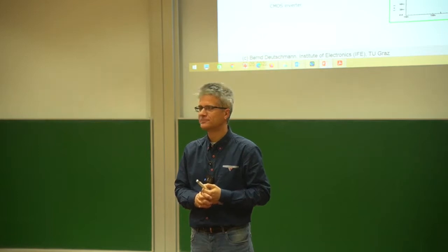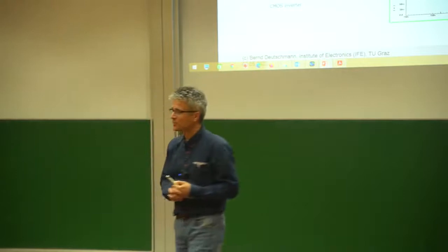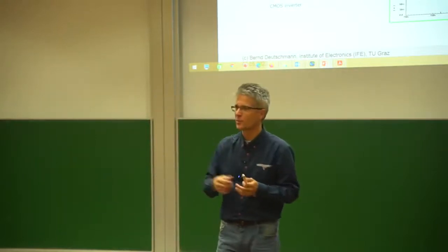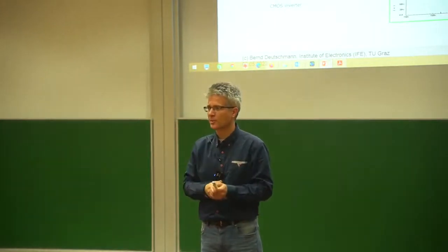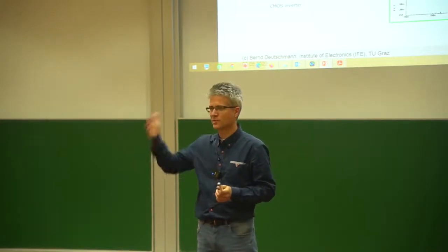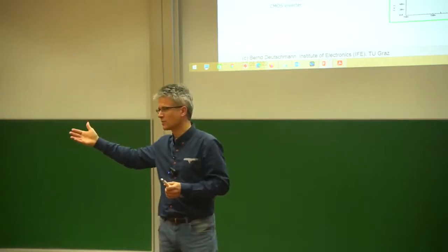Slow slopes, so don't switch too fast. Exactly. Make it as slow as possible. So why is switching fast not good? I think we already discussed it: when we have this trapezoidal shaped clock signal or whatever, and we transfer this from the time domain into the frequency domain, we can see all the harmonics up to a very high frequency range.